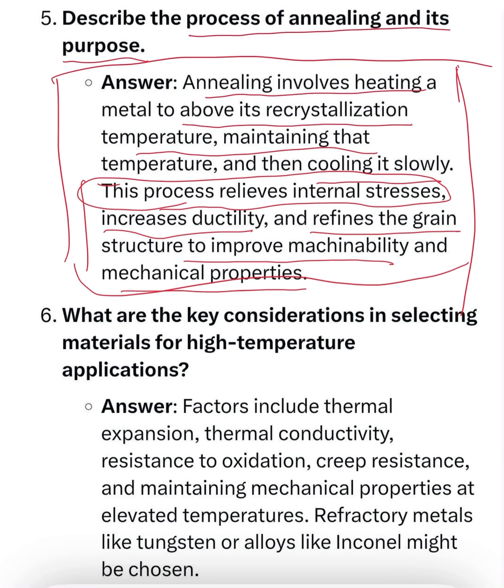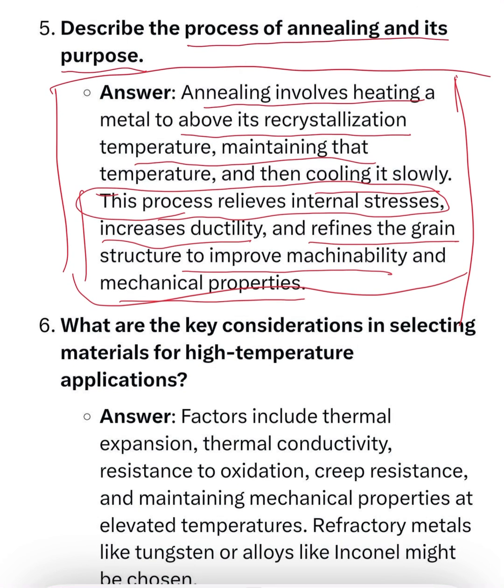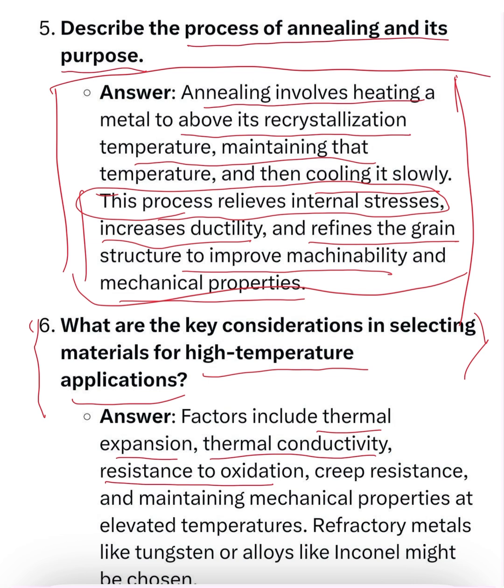The next question is, what are the key considerations in selecting materials for high temperature applications? This is again very important if you are going into an industry that usually works at high temperature. They will ask what considerations should be used for selecting the materials. The most important factors include thermal expansion, thermal conductivity, resistance to oxidation, and creep resistance, which is the most important.